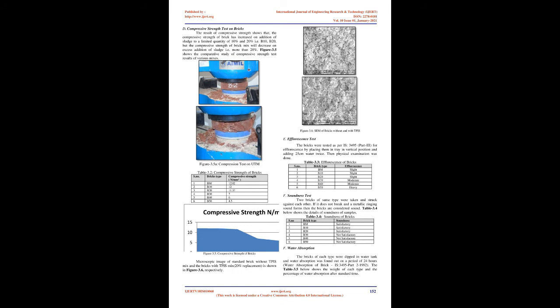The pH of water in which bricks were dipped was tested for a period of 7 days, 21 days, and 28 days and compared with fresh water. Table 3.6 below shows the values for the pH test. I. Thermal conductivity test. Samples prepared were also tested for conductivity after 28 days after the burning process. Table 3.8 below shows the conductivity of samples.